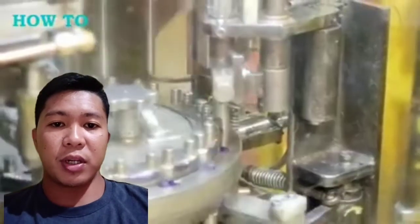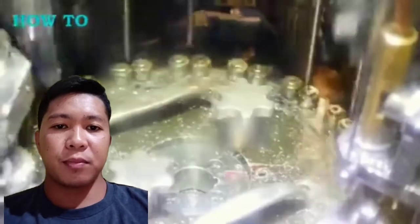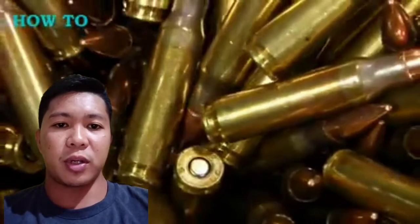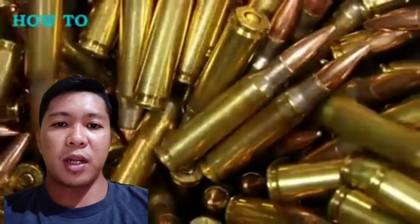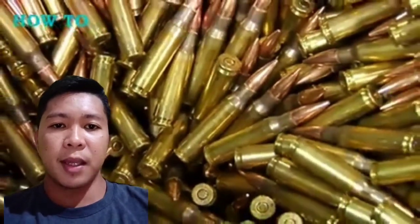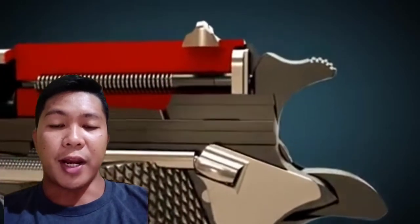Number 1 is drilling. So what is drilling? A special deep hole drill is used, through the center of which lubricating oil is forced under pressure. This operation results in a comparatively raw hole of uniform diameter from one end of the barrel to another.